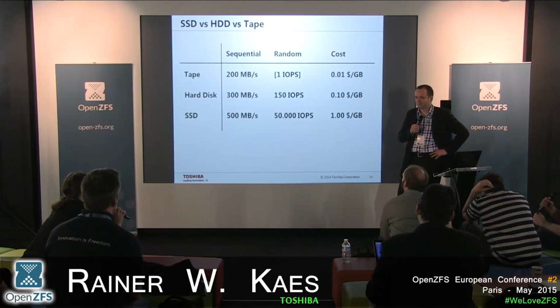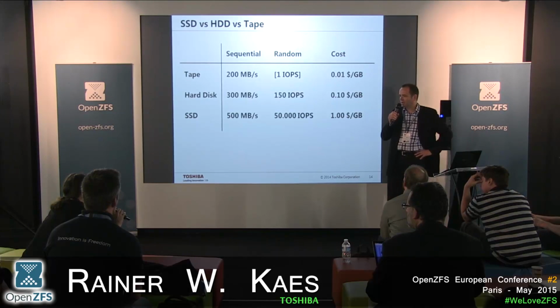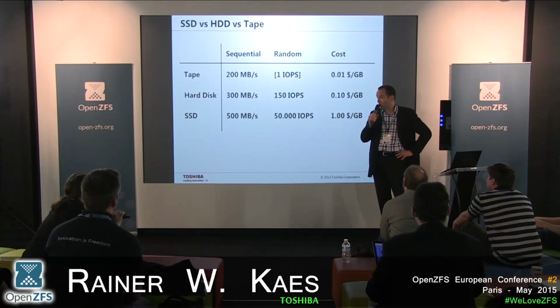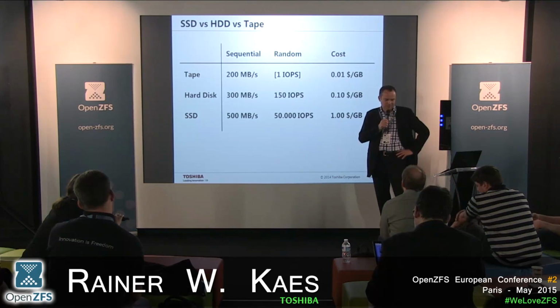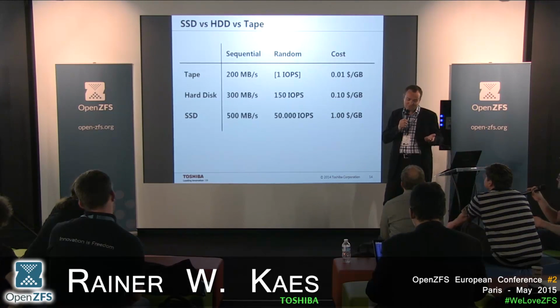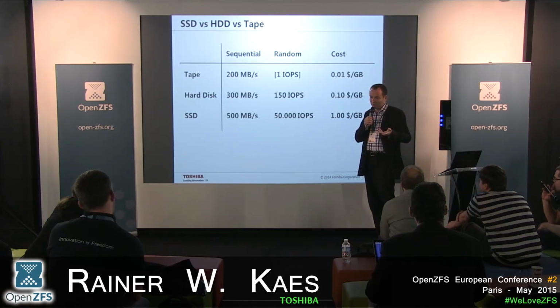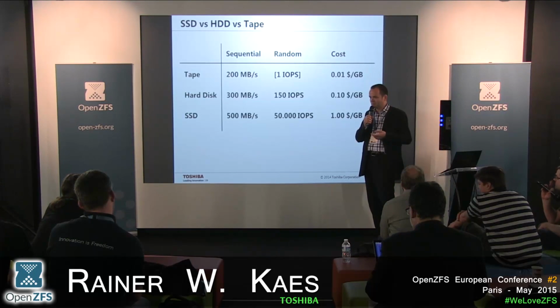It depends on the technology, MLC, TLC. It depends on the underlying flash technology, so there's no common answer to that. Again, it is strongly advised to do a test and monitor your erase counter with the specific workload in your systems. Then you can have the numbers in your system.